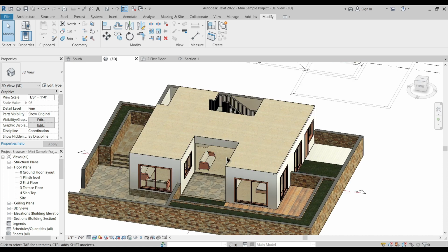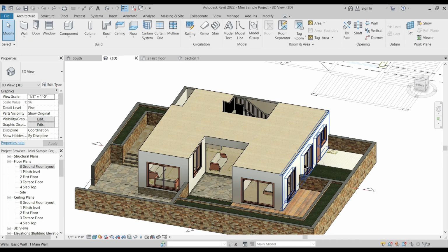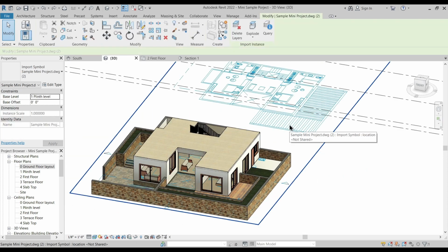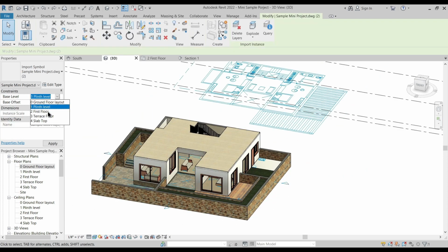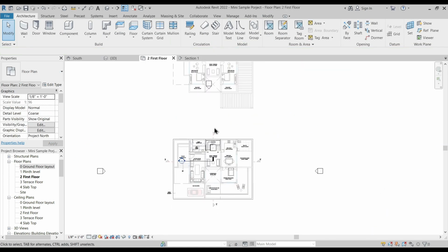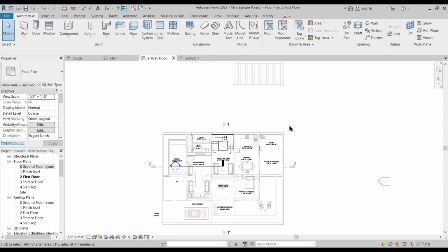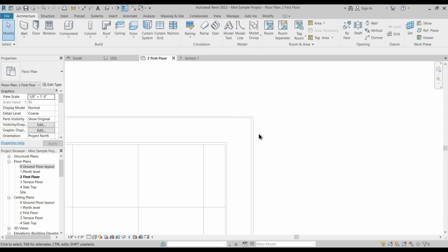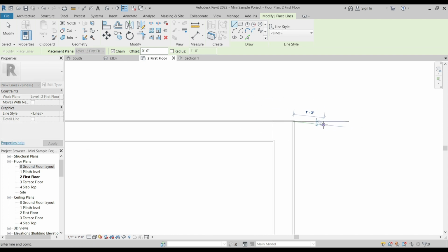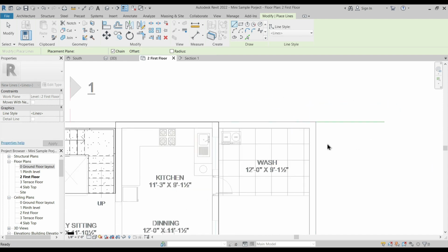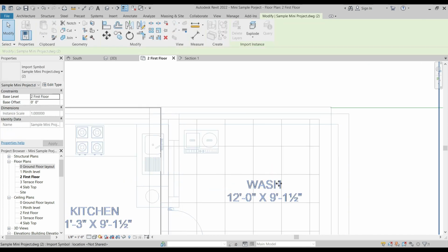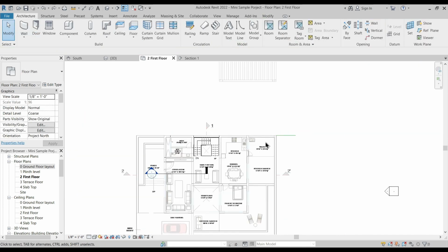Okay, so that was a little bit about the joint conditions of floor and walls, which is typically an important thing in Revit. Okay, so let's quickly start modeling the first floor for this particular model, and for that I need to select this AutoCAD plan and change this base level to first floor, and then go to first floor and align it in place. So for that I need to draw a line onto this inner wall, which is, I suppose, yeah, that's fine.